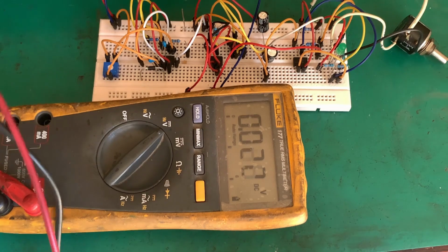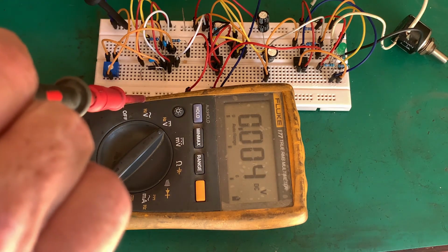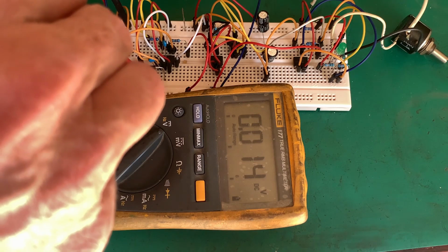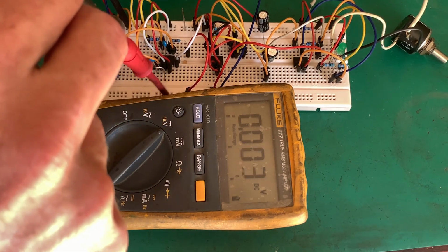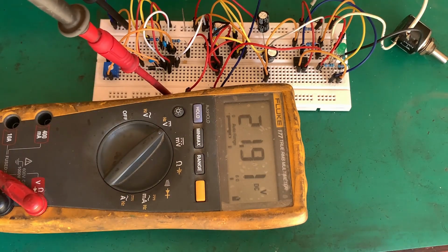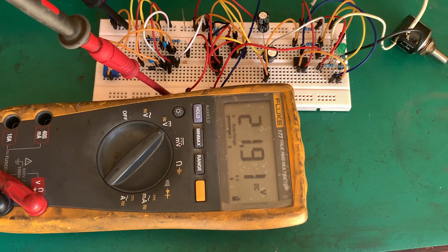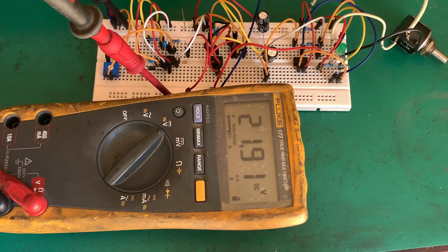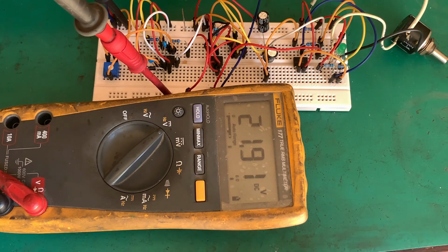my 15 volt rail on the other circuitry is starting to collapse, but if I had a separate 15 volt supply, we could go all the way down to 0. Unbelievable, hey? So by creating a split rail, just for that simple little thing, we have gone and made our op-amp much better. So 10 whole volts extra. But bear in mind, this is all being powered from the 56 volt rail. So my upstream side is starting to collapse.